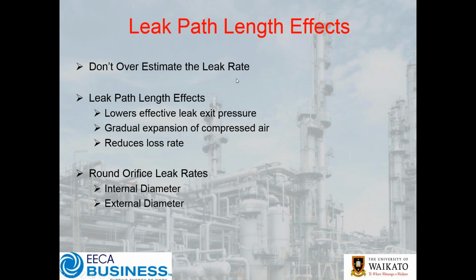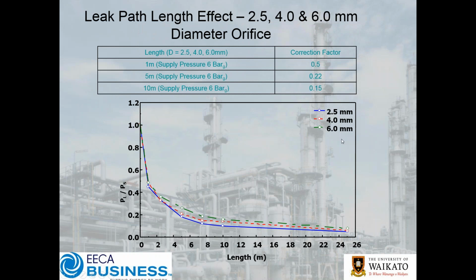Now, the other thing, of course, is generally those tubes have some length to it. They're not just a straight hole. That chart is for a hole in the size of a rather large pipe. So when you add length to a tube, the loss rate drops dramatically. If we can highlight this for you, on the left-hand side we have a ratio of the loss versus what's on the chart, so 1 being the full amount. So if you have a hole in a pipe, you're going to lose 100%. What's interesting, if you go to a meter tube length, you drop to 1/2.